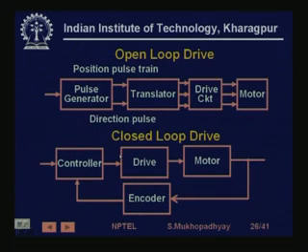Okay. So, you can have two kinds of drives for stepper motors, either open loop or closed loop. In open loop drive you are not taking any feedback, so you are kind of assuming that every pulse that you have given has been executed by the motor. Obviously, this assumption will be satisfied when your pulse frequency is low. So, you are moving slowly, this can be satisfied, provided the load torque is not too much.